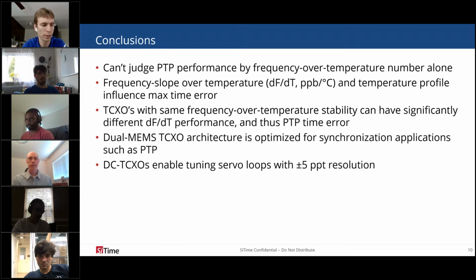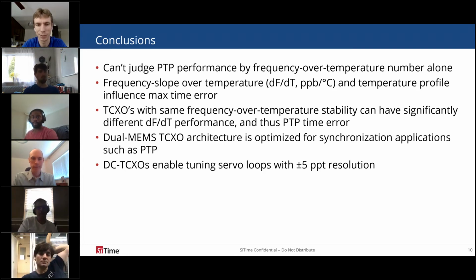So Gary, if I may add, typically all of the precision oscillators, the way they're specified in the datasheet, is targeted for telecom boxes with a very stable environment. And what we've seen is a characteristic of oscillators defined for temperature ramps not faster than 0.5 degrees C per minute or 1 degree C per minute, which is a fairly slow temperature change.